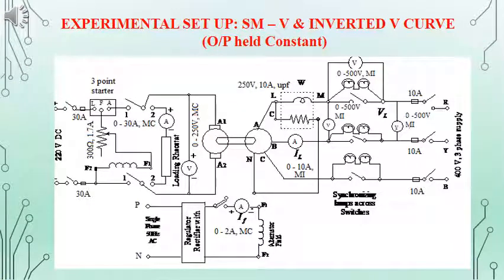So today we discussed the effect of excitation on a synchronous motor, keeping the power constant. We have seen there is a variation in the armature current, and correspondingly a change in power factor too. By changing excitation, the machine can be operated at different power factors.